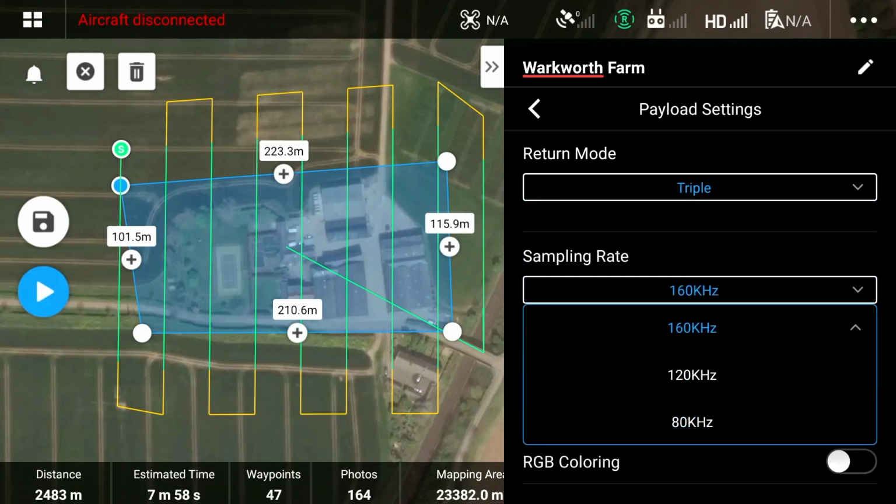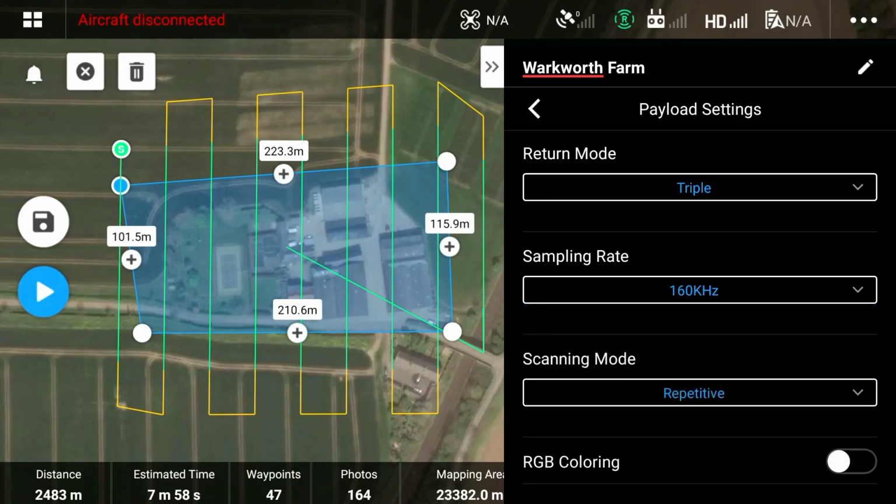In theory, this should measure as 480,000 points per second, but in practice it records a much smaller number of measured points. A combination of dual echo mode and a sampling frequency of 240 kHz would derive the highest number of measured points for a dataset. Therefore, in practice, we recommend dual or single echo mode if you wish to derive a greater point cloud density, whereas triple echo mode is best suited to measuring in areas of dense vegetation.